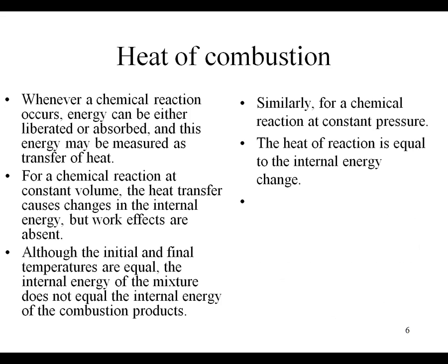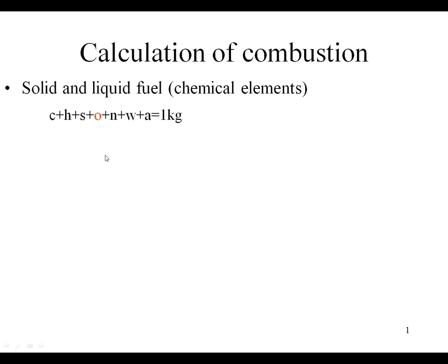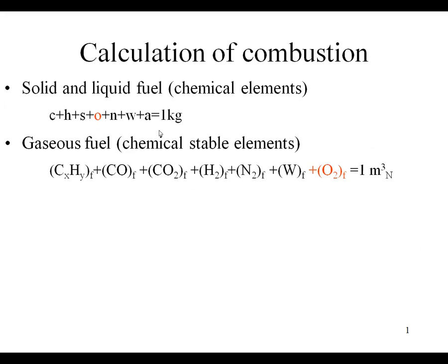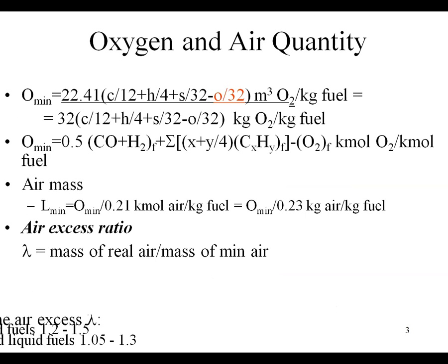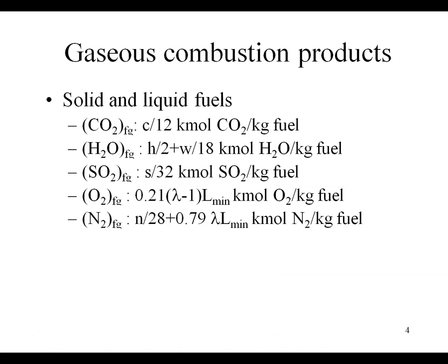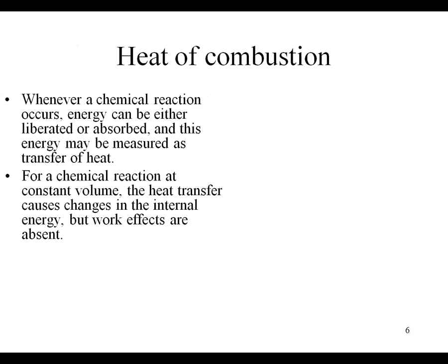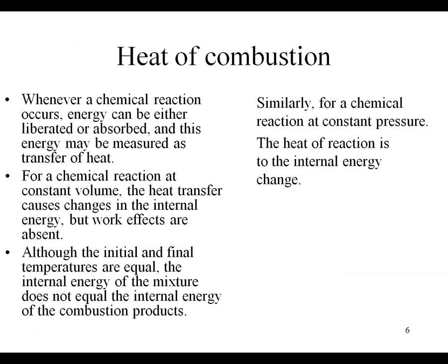And this heat of combustion comes from what? Calculation, from this preliminary chemical analysis, because it depends on how much carbon, hydrogen, sulfur you have, and how much hydrocarbons, hydrogen and CO you have in the gaseous fuel. So the quality of the fuel is first of all indicated by this heat of combustion. That is in close connection to what?